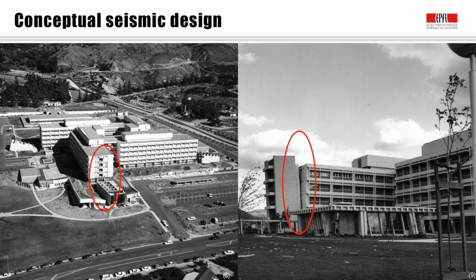Next to this complex floor plan, each wing was also made up of 2 structural systems. So the main part of the wing consisted of frames, and frames are rather flexible. But the end part of each wing was the staircase, and the staircase was built with relatively rigid walls. So these walls are really much more rigid than the frames, and therefore the frames during the earthquake were sort of leaning onto the walls and were transferring their forces to the walls. But the walls had not been designed for it, and therefore these staircases failed. And in the end, 3 of them actually fell over.